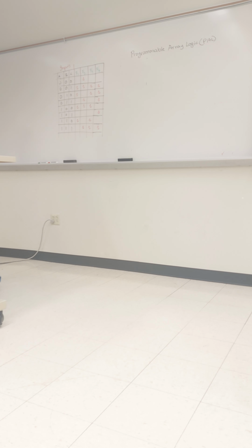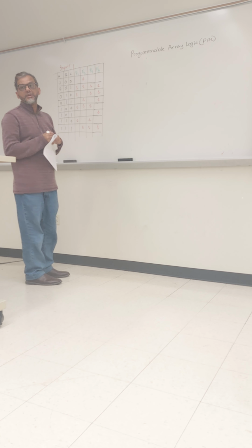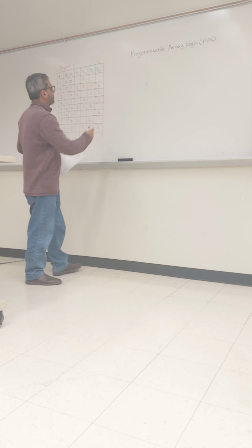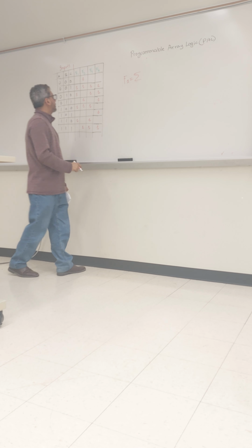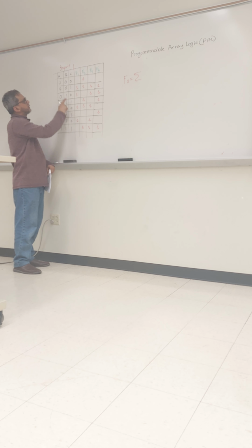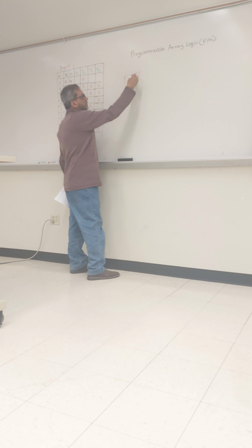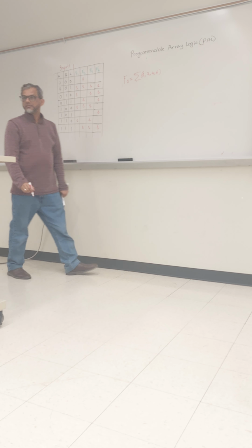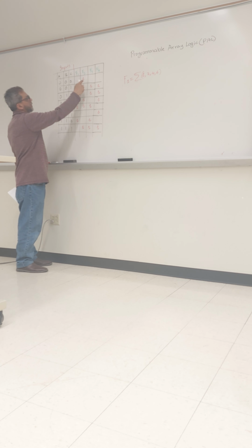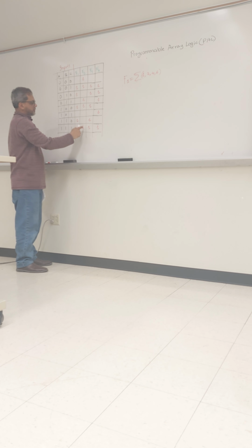So what we can do, as I mentioned, as we have a less number of AND gates, we should try to minimize. So I first write down the min terms for the functions. For function F1, we have logic high for 4 different min terms: 1, 2, 4, 6. For function F2, we have 0, 1, 3, 4, 7.